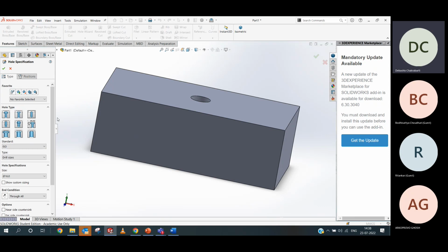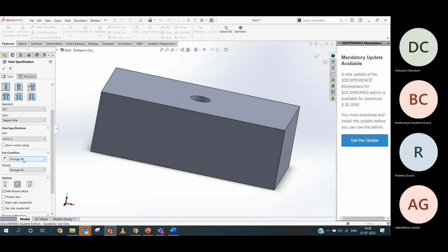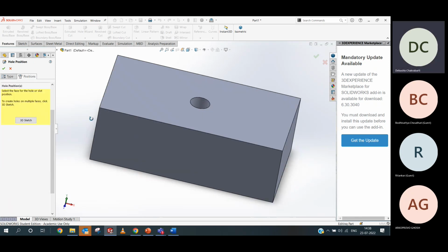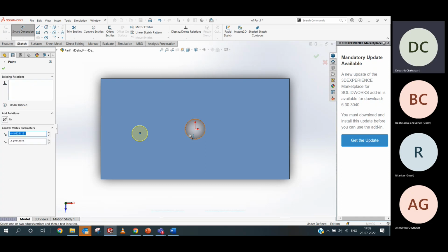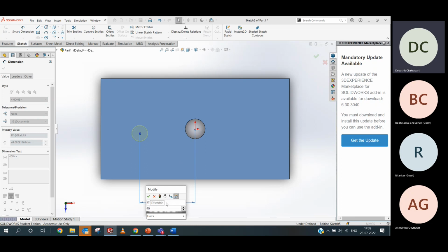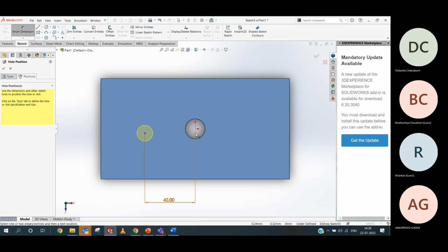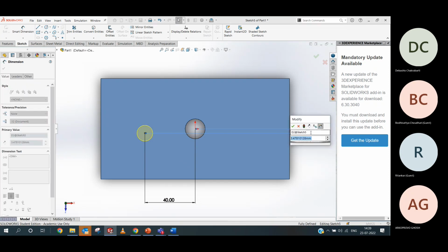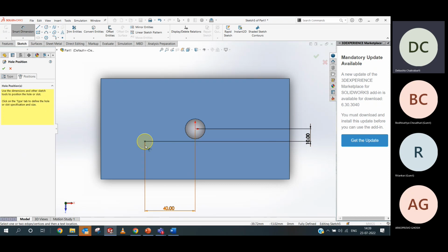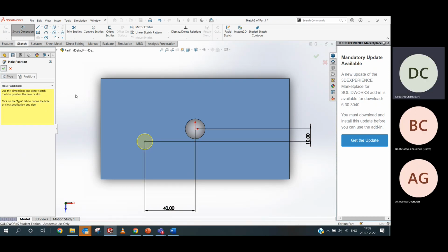Okay. Now see the things. We just define the tapped hole. Select this one. I just tap the hole. Define the hole size here, M14 into 1.5, with thread position like here. We can define the dimensions also here to constrain the hole vertically and horizontally. Now the hole is constrained over here. Click on OK.